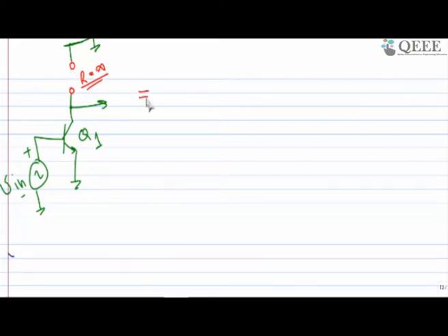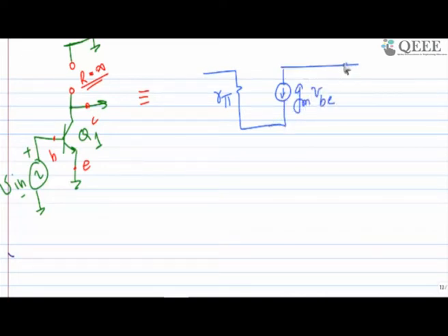And if I draw the small signal model, and replace this base, emitter and collector, you please also draw along with me in your notebook the small signal model of this entire circuit. It has to look like this one: R pi, gmVB. R0 means I am talking about the early effect voltage.